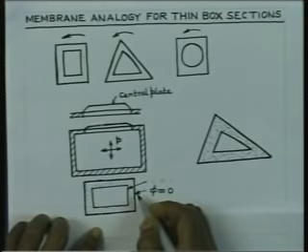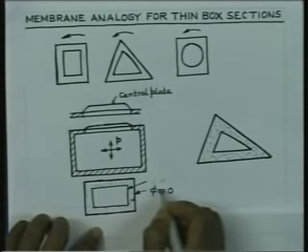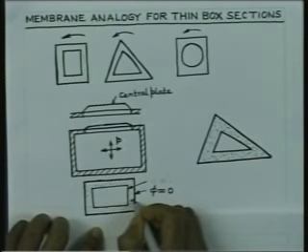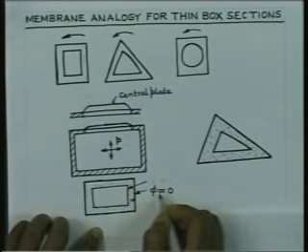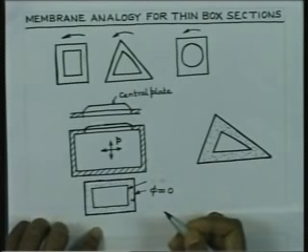It also due to the fact that there cannot be any shear stress acting perpendicular to this boundary. So, this phi is constant along the boundary, because if there is going to be a stress acting perpendicular to this boundary, then the slope along this boundary cannot be 0. But since phi is constant along these boundaries, the slope is 0 in this direction, therefore, shear stress in this direction is equal to 0.